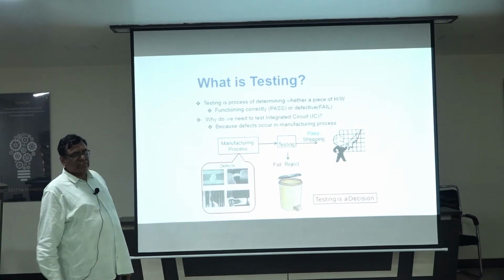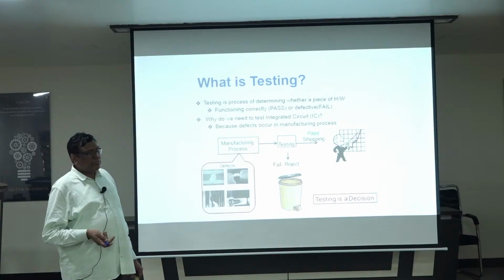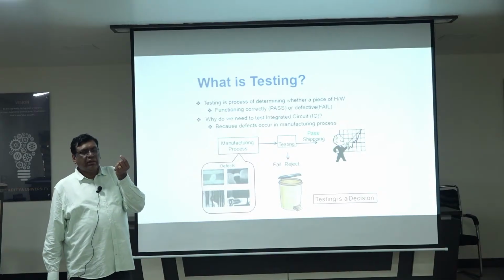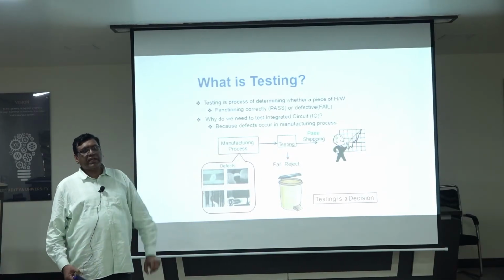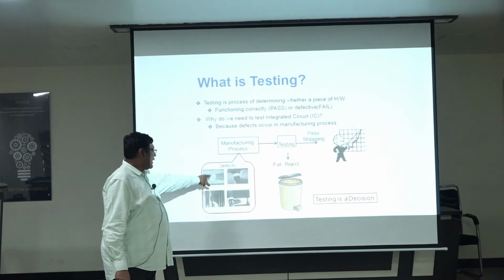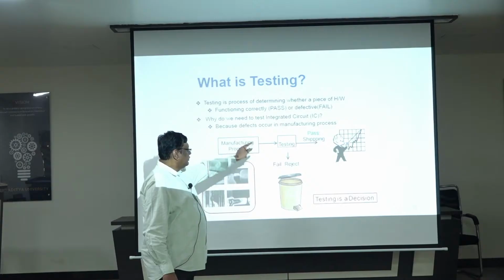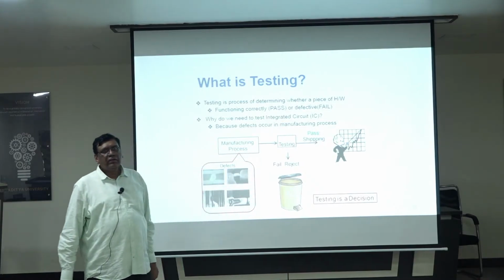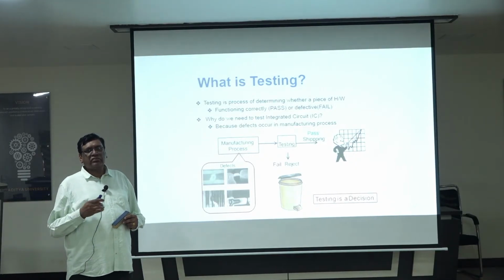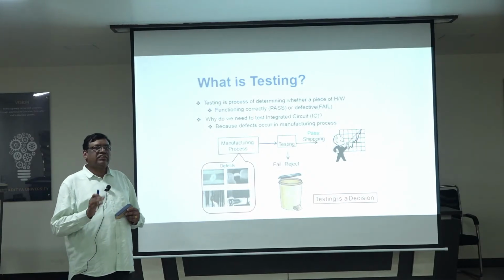Generally, manufacturing testing, our goal is that after manufacturing we have to test it. So how will the defects be there? Some shorts will be there because of tiny particles. They dress up so that no dust particle will enter the fabrication facility, but still they will have some particles that may cause a short. If it is rejected because of failing, they have to throw it out, and only the passing ones are passed out. That means the yield. Suppose in practice, if I manufacture 100 chips, I will throw 30 chips into a dustbin. Only 70 chips come out.